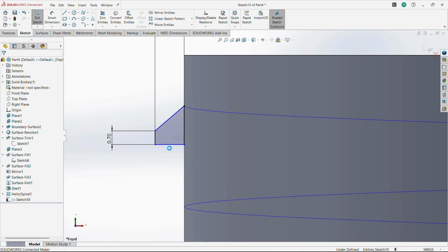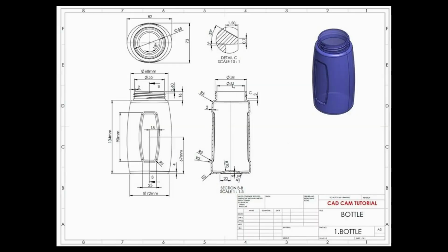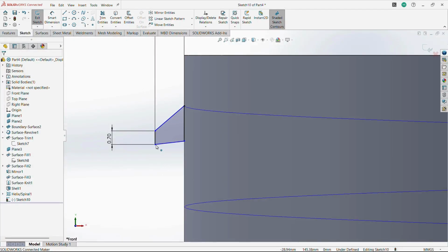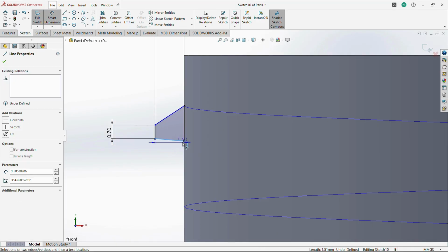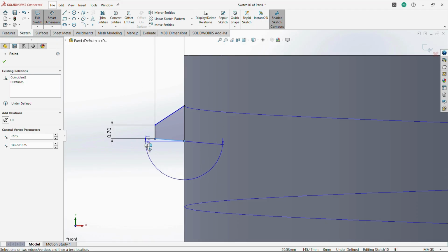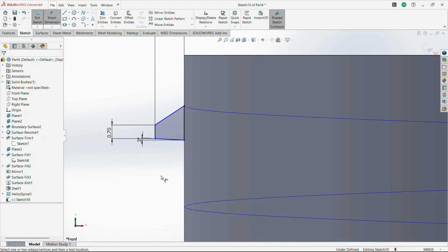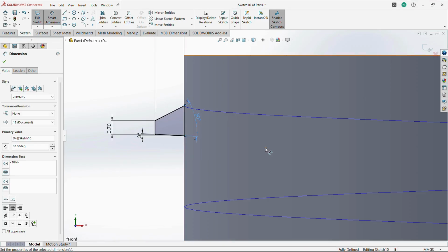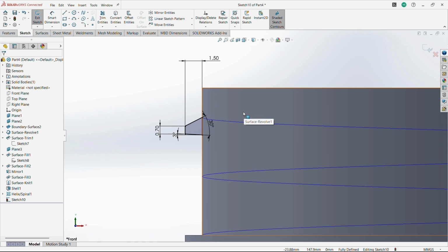So select this angular geometrical constraint and delete it. Afterwards, mention the angular value. It is nothing but 3 degrees. So we slightly change these points and constrain it at the angular value of 3 degrees. Afterwards, what is this initial angular value? 30 degrees. Mention this angular value. The total profile is fixed under these dimensions and is also fully constrained.